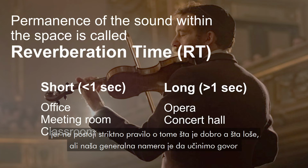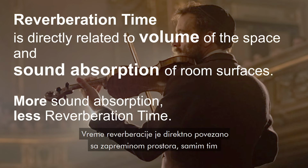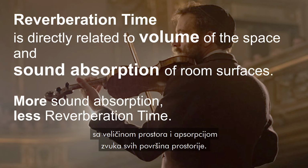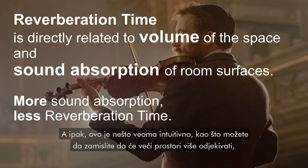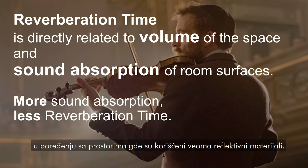But our general idea and our target is to make the speech intelligible and to make the music strong and clear. And we use reverberation time as the convenient way to express and quantify that. Reverberation time is directly related to the volume of the space, therefore to the size of the space, and the sound absorption of all the room surfaces. Again, this is something very intuitive: you can imagine that a larger space will sound more reverberant, and a space with more sound absorption, so with more soft elements, will sound less reverberant.